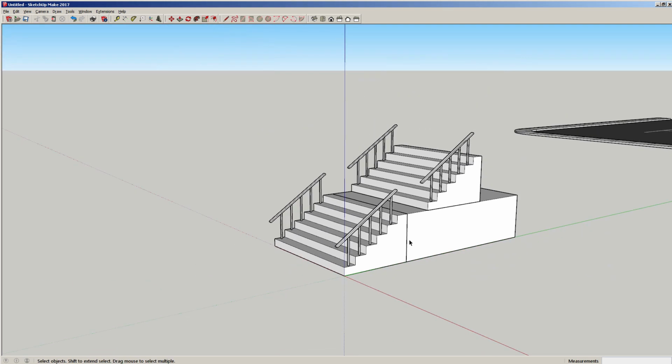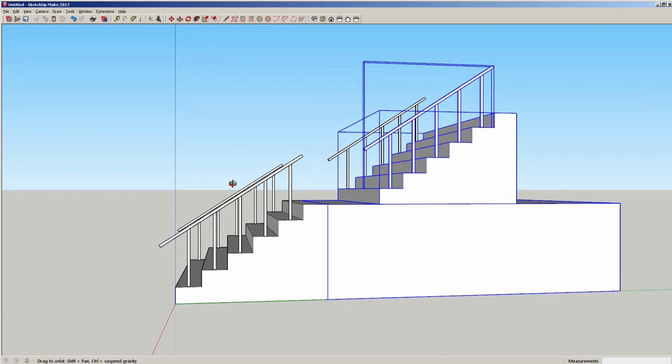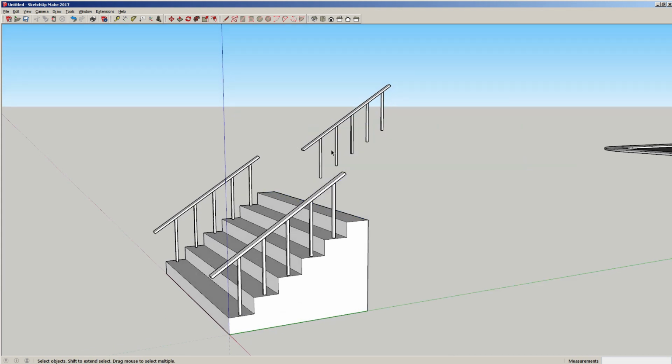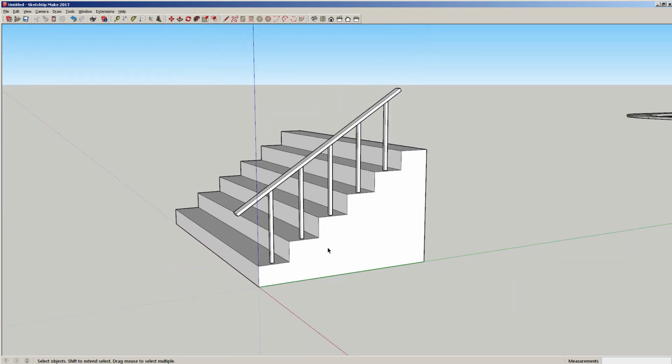Alright, so what's next? We're going to do bump to bar. Let's make this easy. Let's go ahead and reuse our rail here. So I'm going to delete all of them but one. And I'm going to keep these stairs here too because that'll show the angle of our bump to bar. The first thing you want to do is click at the very top corner. Oh, let's not do the top because remember we made this a little too small. It's not exactly 8 inches. Start here. And snap to the top corner at the bottom, right? Here.